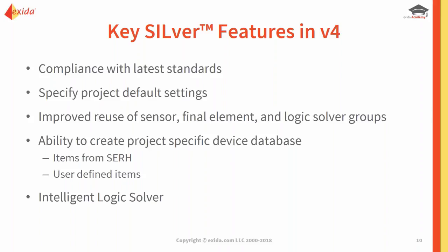significantly enhanced the logic solver to the point where we take into account how you wire the field devices into the logic solver, and how you wire an I/O channel onto an I/O module, and we can basically create a virtual image of your eventual cabinet with the knowledge that we have within the tool.